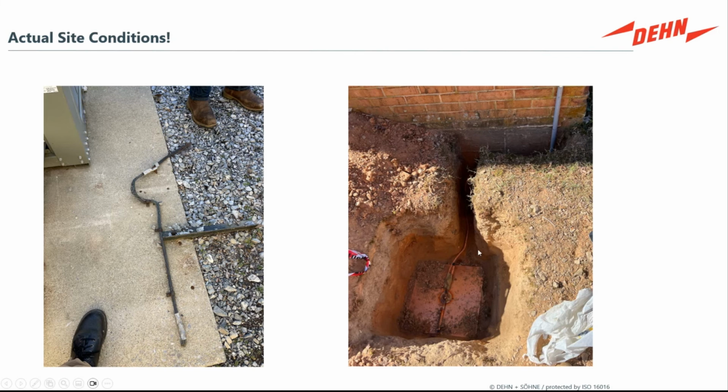Here you can see off to the right is a really good illustration of bonding plates, grounding plates, where you're using a plate to create the equivalent surface area in an attempt to disperse lightning into the soil in very space constrained and otherwise challenging areas where you can't install other systems.